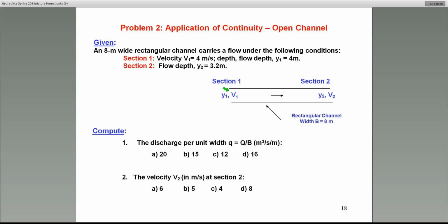Also, we have the average velocity, just like we had in the pipe system, except that the average velocity is a little more difficult to define in an open channel system. But for this part of the exam that you're taking, I would just leave it at that. Typically the average velocity will be given to you. If not, keep in mind the average velocity can always be calculated using the flow rate: Q over the cross-sectional area will give you the velocity from the continuity equation.